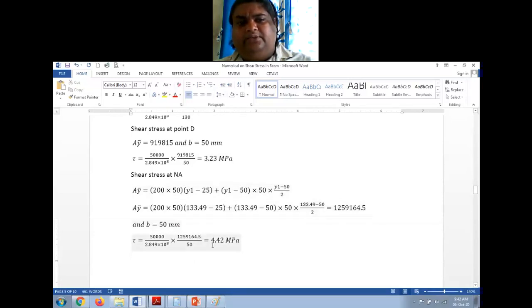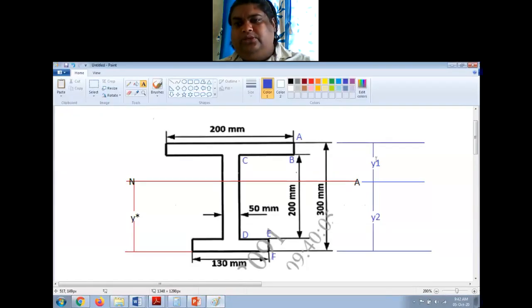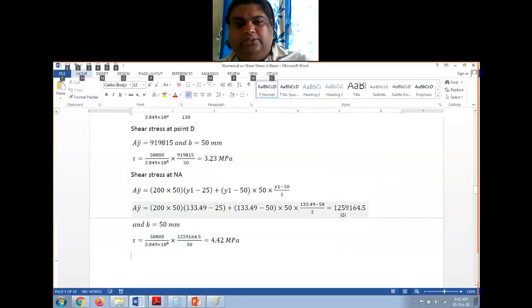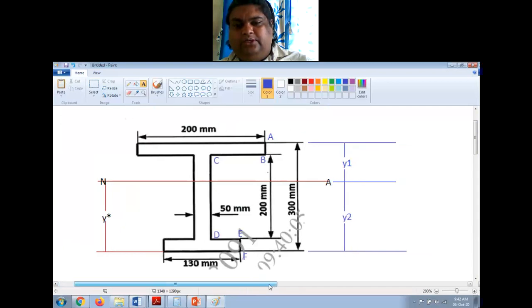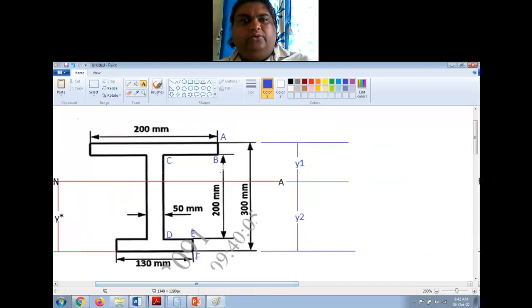Now, if you use the dimensions as A, B, C, something like that, and you find the formulas for finding the shear stress for all this section, you will find that those equations for shear stress will be parabolic equations. So the shear stress distribution along this is parabolic. Now you have to draw the shear stress distribution curve. So what you have to do is you have to first project all these lines or all these points. So just projecting these now.